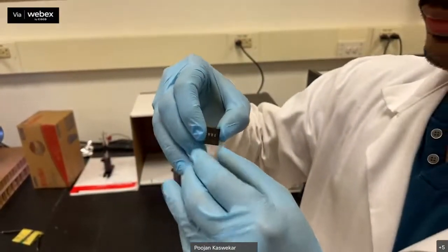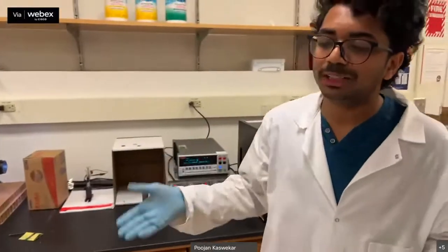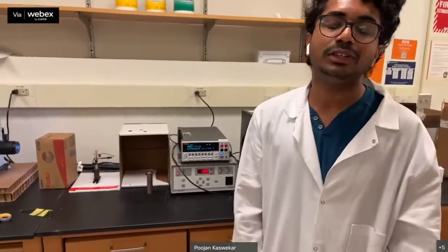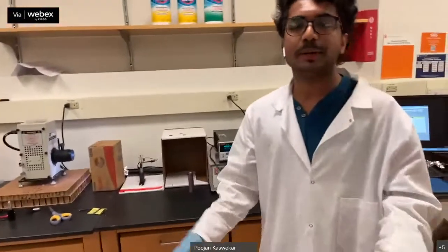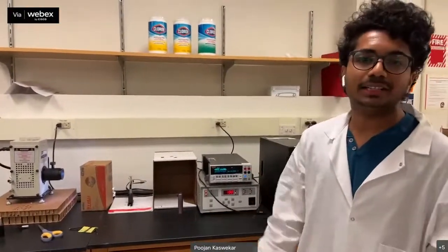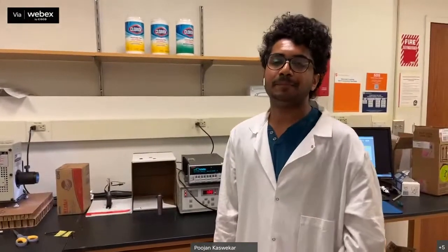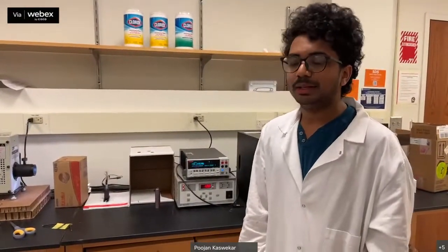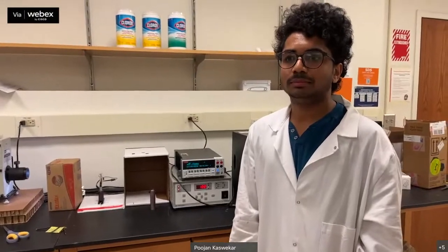Raja, his question is there. Are you using only the exposed area, or are you also considering the metal contact area? It's only the exposed area, Dr. Yes. It's not the metal contact area because you are not exposing that metal contact, so it's not generating any electrons or holes from there. It's not generating any charge carriers from that area. Your light is not going through the metal, because this one is metal, so it's reflected back. So only in between the fingers, we have to consider how much area is there. Exactly.